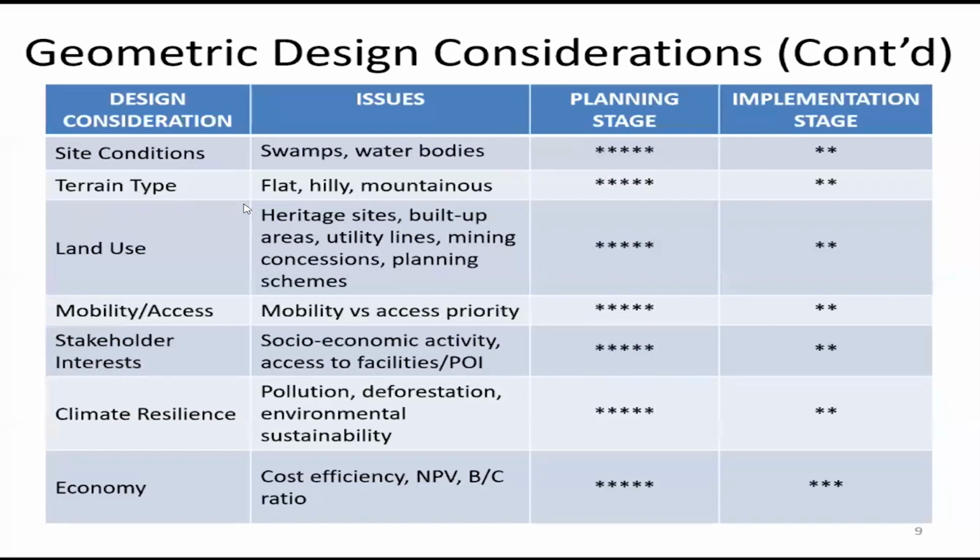Are we, by some mistake, going to erase a pond or wetland that houses some particular bird species or animal species, or flora and fauna? Can we modify it? The trees that our geometry is affecting, what can we do? Can we minimize deforestation, or what are the mitigation measures? All of these are geometric design considerations.